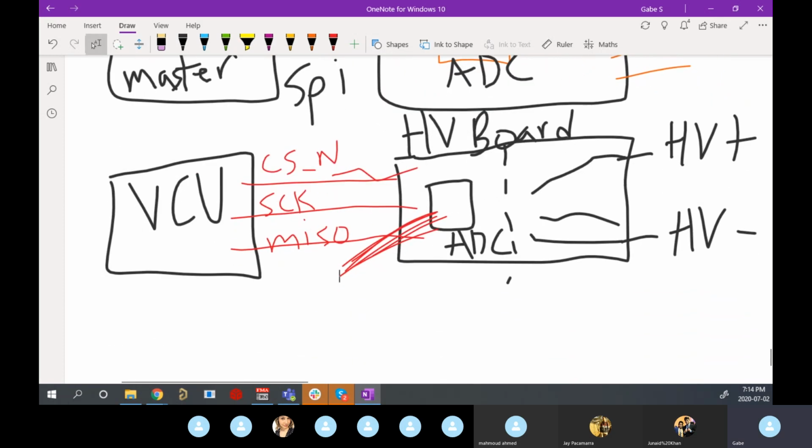To actually engage chip select in our code base, to assert this low and start the clock to send data, we don't do this manually. We don't say, all right, set chip select to low, now for clock, go 1 0 1 0 1 0 really fast. We don't actually do that. The drivers take care of that for us.